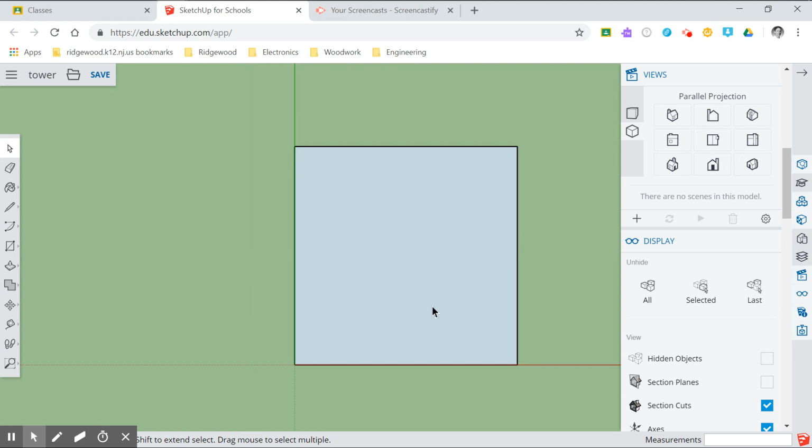So what I need to do is put a center circle in this drawing. I'm going to select here under the rectangle, the circle tool, which is in the middle, and I'm going to try and find the center. Now, I can't find the center by simply hovering around it. SketchUp won't understand that. It only tells me that I'm on the face or I'm on the line. Now, lines, it will always be able to find a corner, which is an endpoint, or a midpoint. So it will always snap to those points.